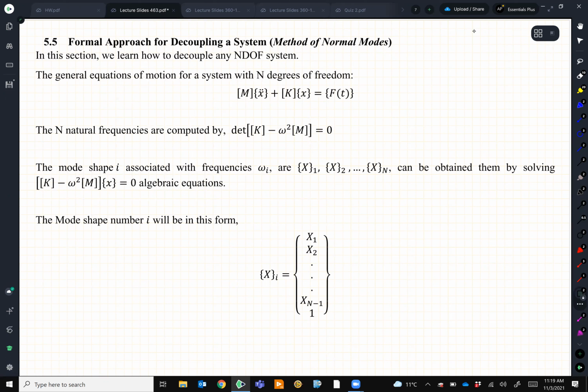So moving one step back, with the two examples that I just solved, what happened with them? We had a coupled system, a 2-degree coupled system. We turned them into two independent systems. Why did we do that? Because a 1 degree of freedom system is easier to deal with. We know how to solve their equation if they have, for example, external force. That's better. Our goal here is to convert an n degree of freedom system to n independent 1 degree of freedom systems.